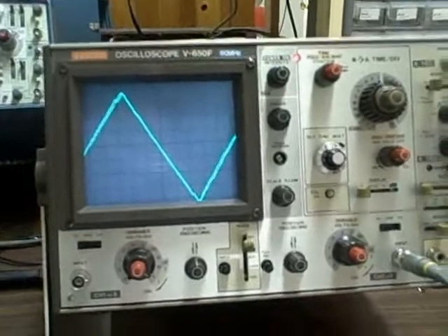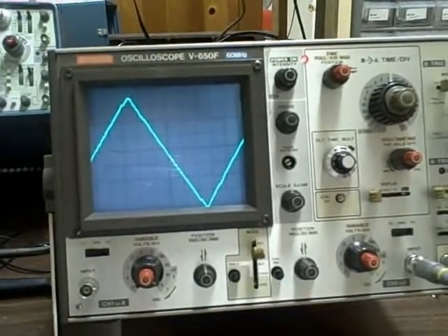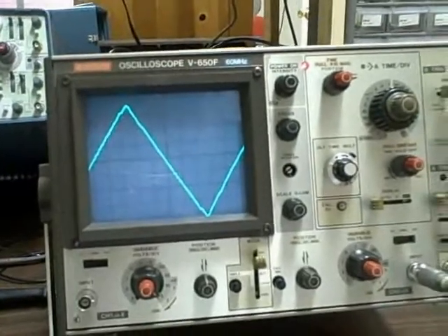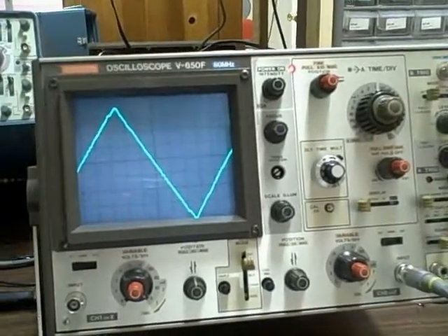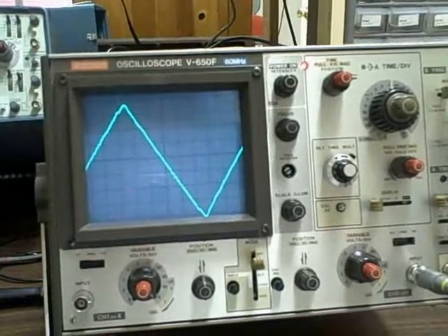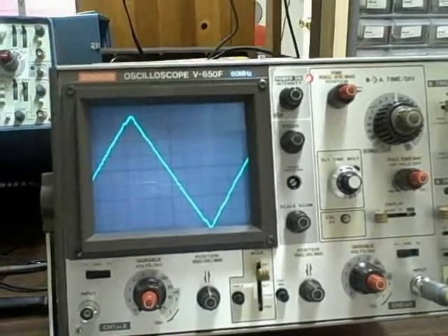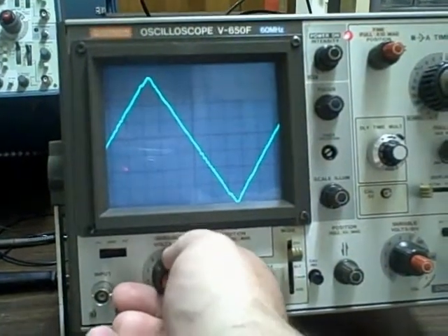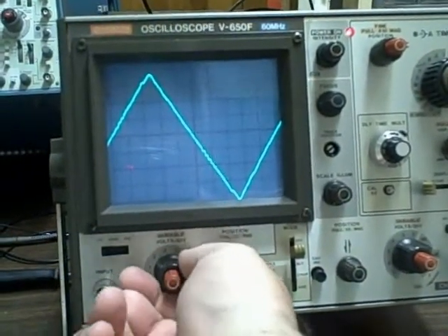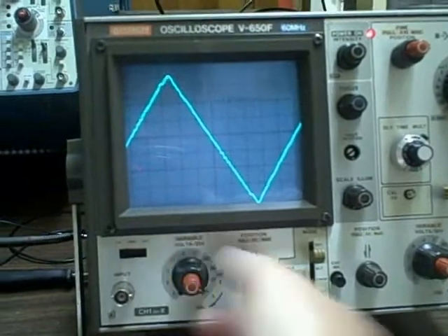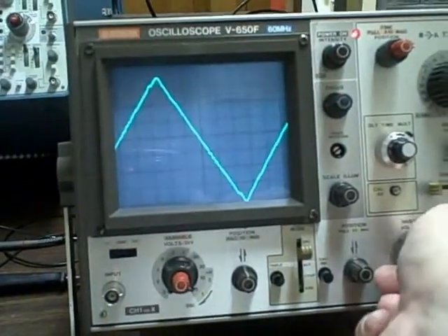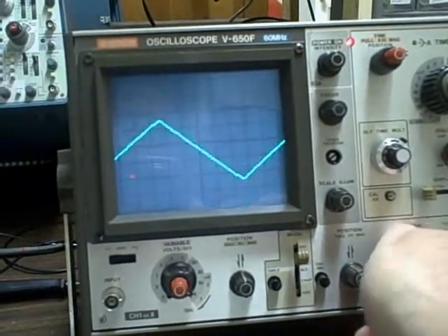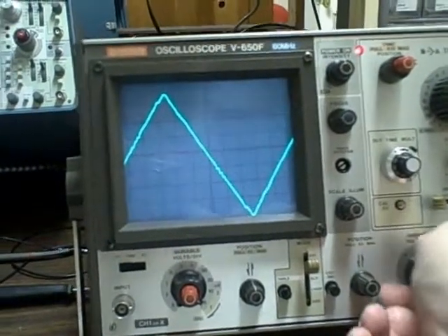I wanted to demonstrate that during the calibration steps I was going through, I noticed that both channel 1 and channel 2 were noisy at the lowest steps, and I went ahead and opened it up and carefully cleaned the switches, and you'll notice now that on the lowest steps there's no jitteriness, nothing displayed at all.